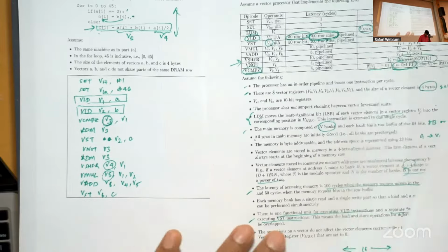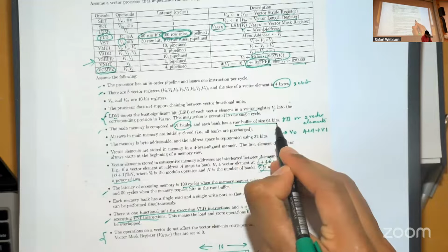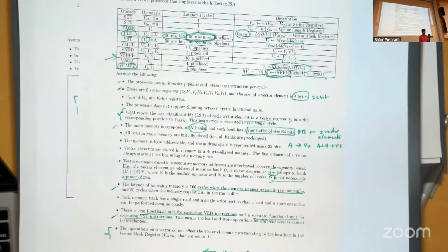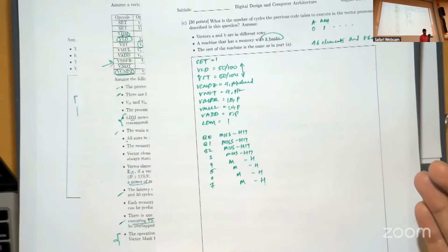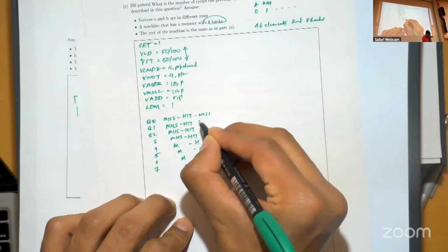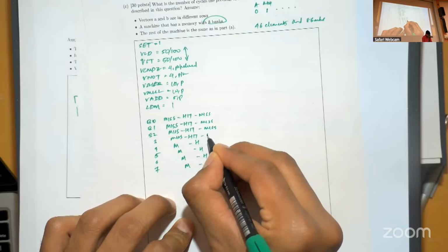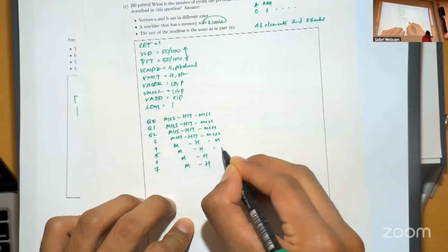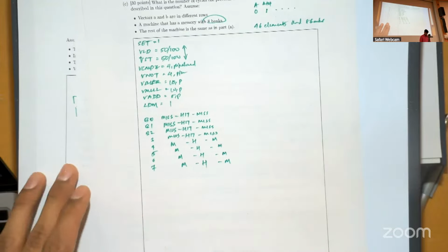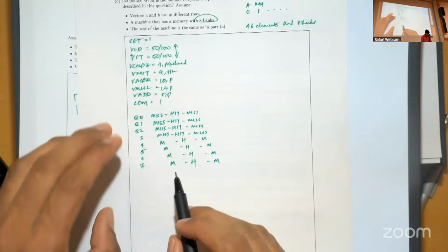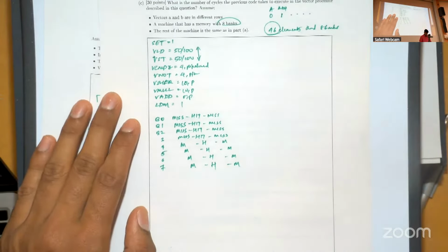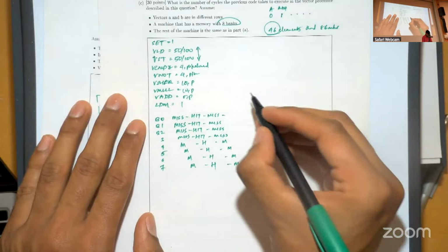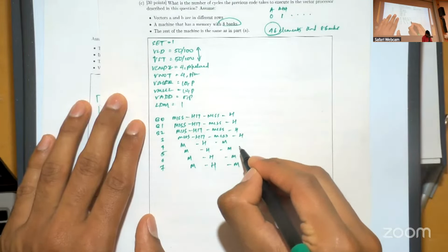However, we know that our row buffer size is 64 bits, which is really 2 vector elements. Therefore, after a miss and the subsequent hit, you will have to access a different row, which means that you will have another miss for all of these. And I will fill it like this. In total, at this point, we've accessed 8 times 3, 24 elements. But we need 46 elements, which means we can keep extending this until we complete 46.